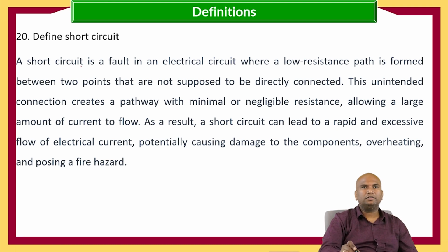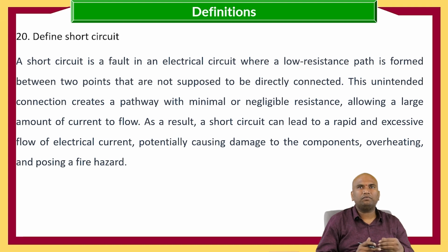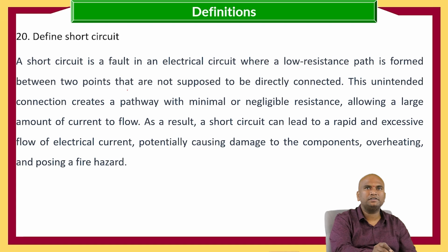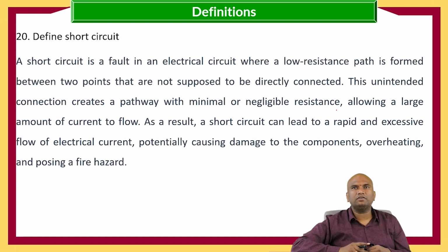Define short circuit. A short circuit is a fault in an electrical circuit in which a low-resistance path is formed between two points that are not supposed to be directly connected. This unintended connection creates a pathway with minimal or negligible resistance. The short circuit has minimal or zero resistance.